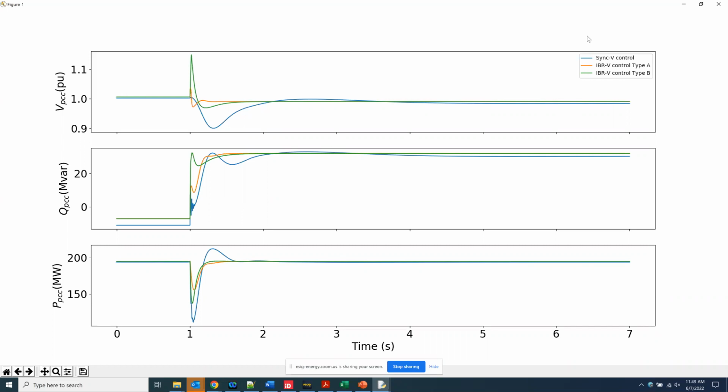But if the intention of grid forming is from an overall system stability perspective, trying to improve the stability in a weak region of the network, trying to maintain stability when the last synchronous machine trips, trying to provide adequate frequency response, adequate voltage control, if we want all of that, let's think that synchronous machine was an inverter. If we want to continue to operate a 100% inverter system where we need grid forming resources, and we have all of that as our perspective on grid forming, then that machine wouldn't classify as grid forming.